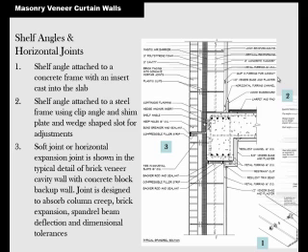So this is your structure behind, which is obviously a concrete floor, and there's a concrete beam. Then you've got some concrete blocks. I don't know if any of you are actually doing masonry cladding for your project, but this is a good example. Then you've got your 2 inches of insulation on that side. Then you have an air gap, and then you have your brick.